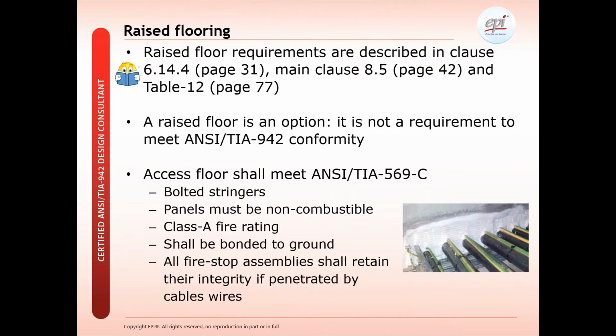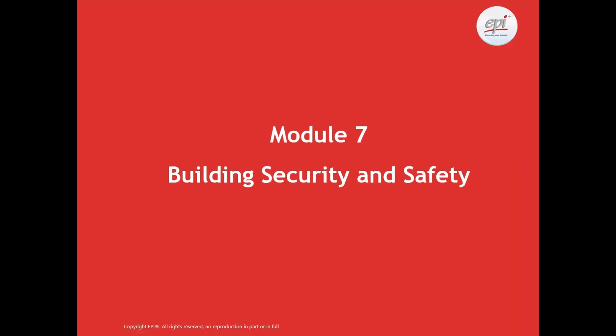Many data centers are still using raised floor systems because of the flexibility they tend to give from a cooling perspective. So during our training, we'll look at how to build and design a data center, again according to the ANSI TIA 569C standard, which is referenced by ANSI TIA-942. And here we have a list of attributes that you should apply when installing and designing a raised floor.